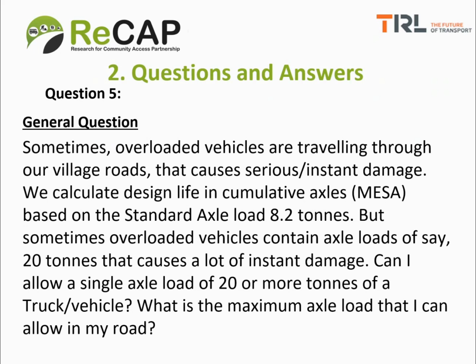We calculate design life in cumulative axles, that is in million equivalent standard axles, based on the standard axle load of 8.2 tons. But sometimes overloaded vehicles contain axles of, say, 20 tons that cause a lot of instant damage. Can I allow a single axle load of 20 or more tons of a truck or vehicle? What is the maximum axle load that I can allow in my road?